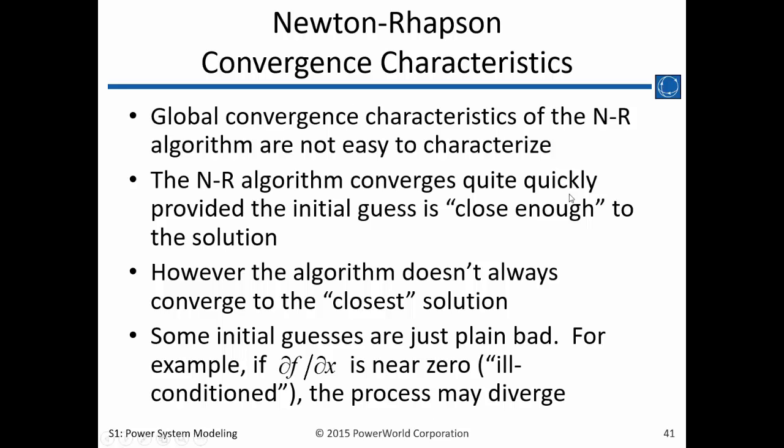Okay, so there are definitely issues with the Newton-Raphson solution. It's not absolutely perfect. You will find situations where you try to solve a power flow or any other type of equations using this iterative Newton-Raphson, where depending on where you start, you may not be able to reach an actual solution.